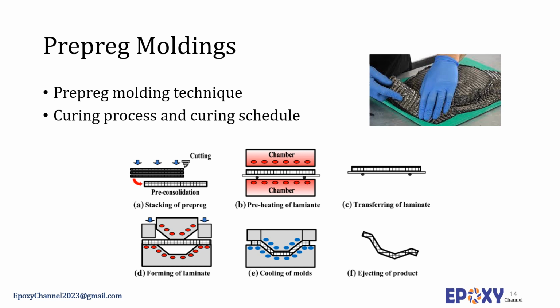The resin viscosity is adjusted for the appropriate tack by adding thermoplastic polymers or advancing the resin with partial reaction with the hardener. The prepreg is stored between plastic release film in a sealed container in a freezer to avoid moisture absorption. After thawing and temperature equilibration, the unidirectional sheet is cut to appropriate dimensions and stacked at predetermined angles to produce a desired laminate.